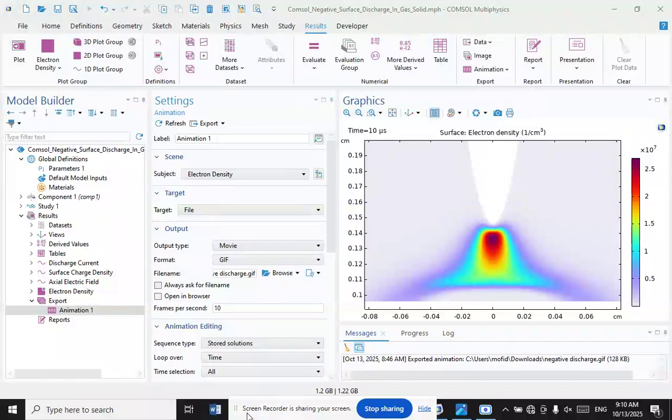The experimental and simulation results show that the surface discharge of polyimide films under high-frequency sinusoidal voltage develops from corona generation to streamer discharge to surface flashover. The surface discharge shows a strong polarity effect, and the number and amplitude of positive half-cycle discharge are both greater than negative half-cycle. The damage of the discharge process to the insulation surface leads to the electric field distortion, which affects the development of the discharge.